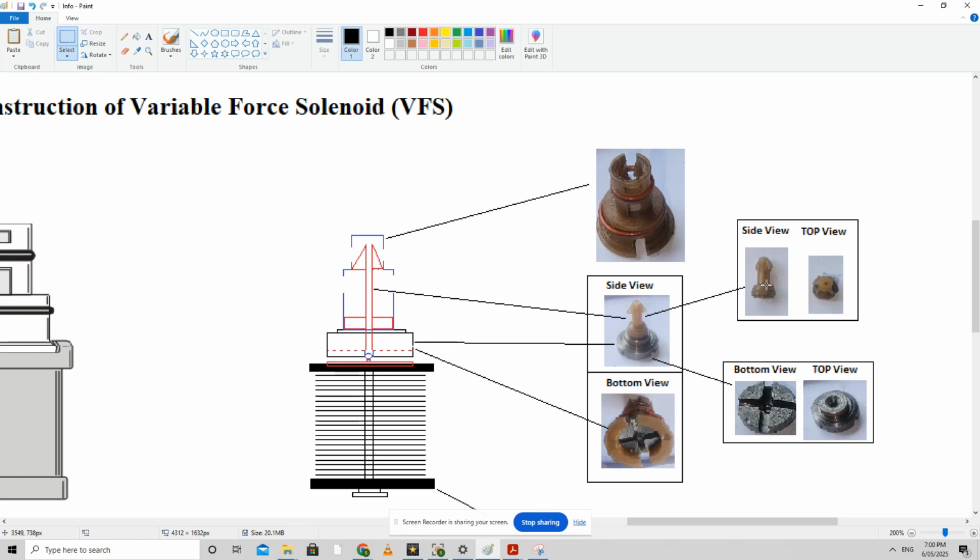One is this small plastic tower that goes on top of a metallic circular disc. The metallic circular disc has a hole on top, and on the bottom it has four lines, four pathways for fluid discharge. And if you look at the top of this plastic piece, there is a small hole in the middle. So when it is placed over here, the fluid has a freeway and can access the vent of this solenoid via this pinhole access. So this is usually open.